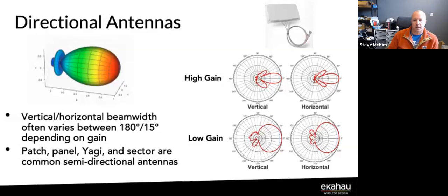You still have your side lobes on it, but size wise, a 23 dBi dish in 5 gigahertz is about 18 inches, so it's not huge. Obviously, the bigger you go, the more gain and the more focus you get out of it. If it's a really short shot, I would usually look at an even higher frequency, say 24 gigahertz or 60 gig, but that's kind of beyond the scope of this webinar, I suppose.